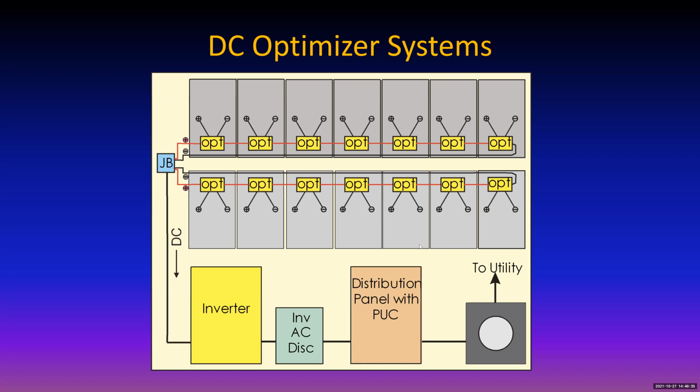Let's see. Isn't it always live as long as the sun is shining? The module itself is live as long as the sun is shining. So up to the input connection to the microinverter, it's live. Okay, and there's nothing much you can do about that other than to put something over it to cover it. But you would have to touch the inverter leads in order to have any damage. The microinverter itself goes down. There is no AC output from the microinverter, and the microinverter is installed directly underneath the module. So I hope that is what you're asking about, Sheila.